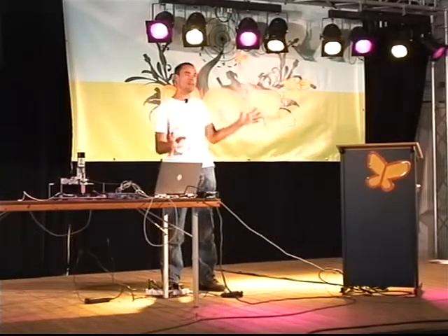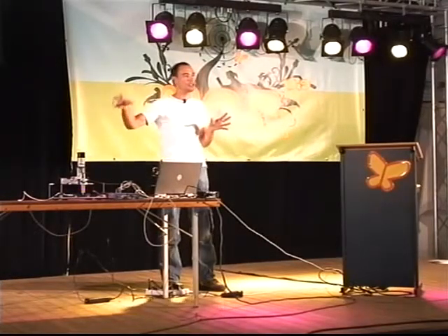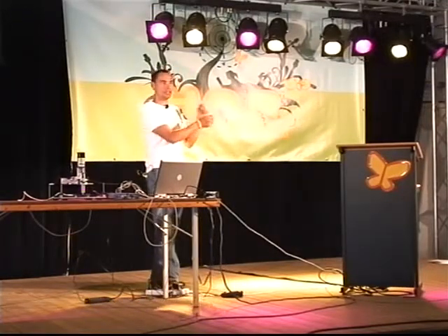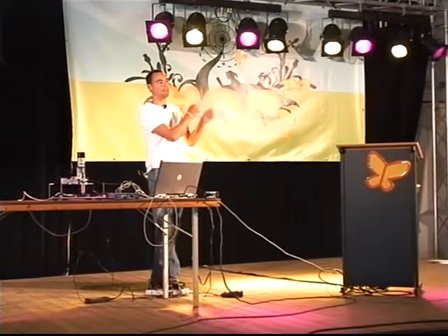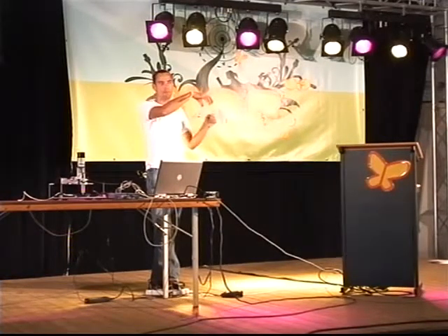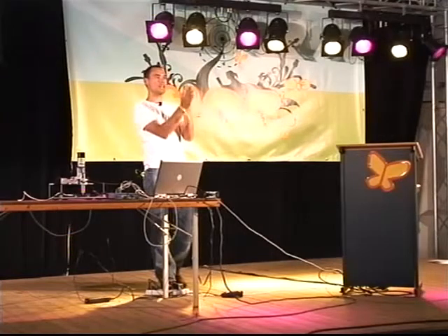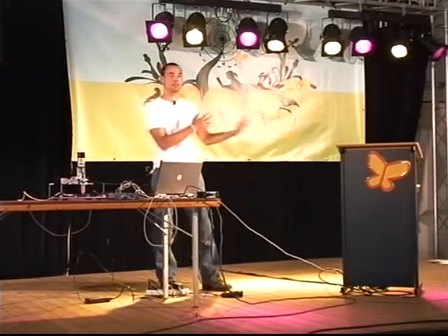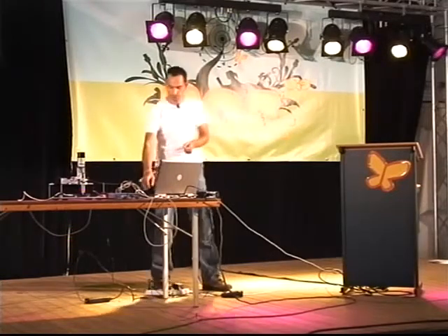One thing that you can do with timing, with power measurements and EM measurements, is increase the accuracy. Like I said, if you have a smart card and you can just see input and output, if I measure the power signal of that same chip when it's happening, I might see timing variation in the power signal. And then still it's a timing attack, but I use the power signal to do it.